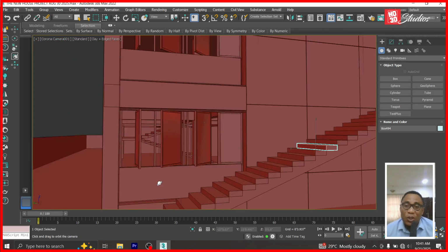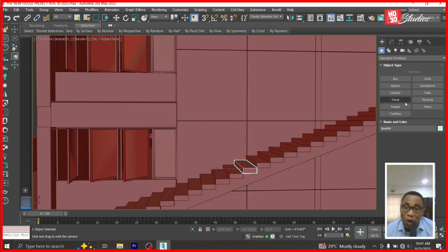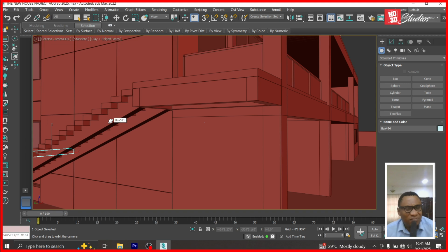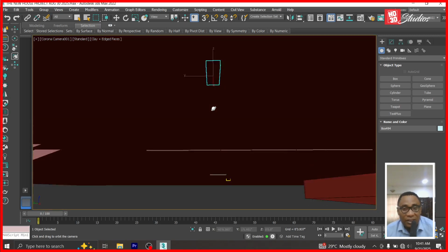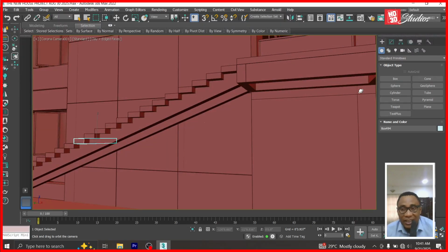So you can build all this, create a wooden formwork of all of this, and pour your concrete inside, or you can build this individually. But these beams, I'm almost certain that these beams would have to be built in situ, on location, on site, just where they should be. So they would have to build a formwork for this beam, and then this. So this can be built separately. The stair landing can also be built separately and then placed with a crane on this.